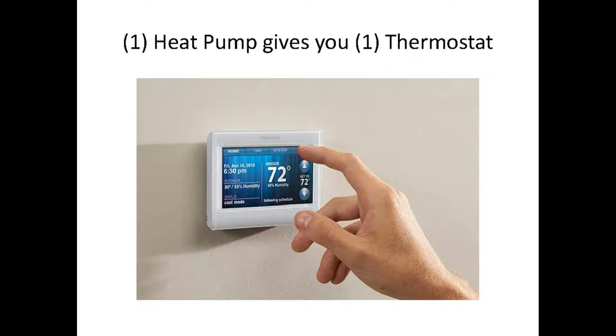And there's a lot of comfort effects from choosing upstairs versus downstairs. The best way to do a two-story house is to have one heat pump for the upstairs and one heat pump for the downstairs. And you'd have a thermostat upstairs and a thermostat downstairs. Okay, and we struggle a lot with providing an adequate number of thermostats with our various HVAC equipment that we put on our drawings. We'll talk more about that later. Okay, next slide.